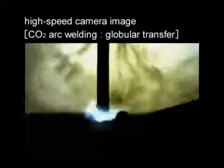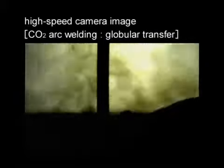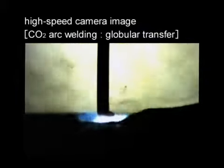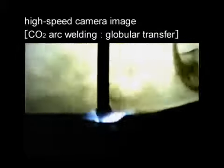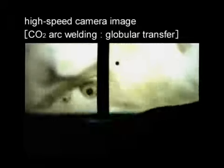In this mode of transfer, the wire generally does not short to the base metal, therefore the number of short circuits is less when compared with that of short circuit transfer mode. Globular is in the range of 10 to 50 times per second. Therefore, the arc sound is loud and the arc is less stable. Large spatter balls can occur. However, higher arc energy is obtained.